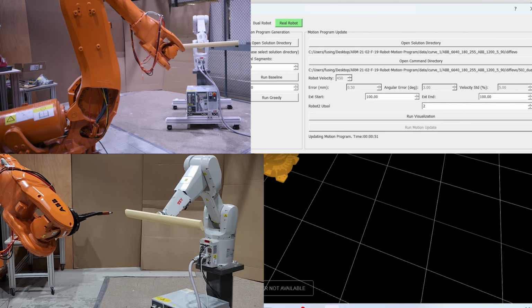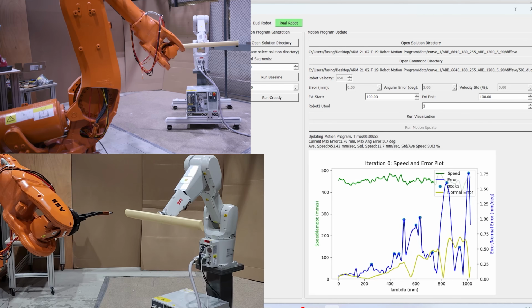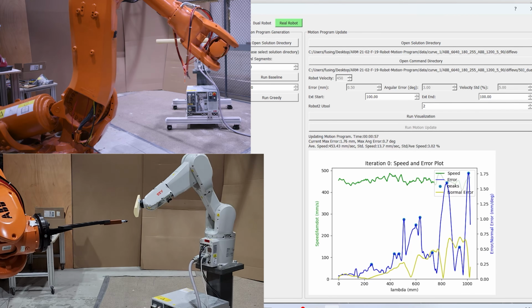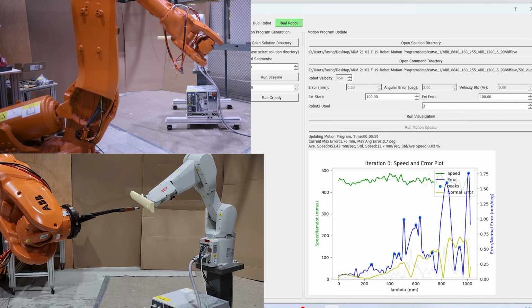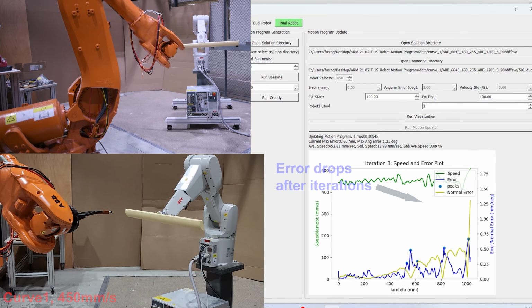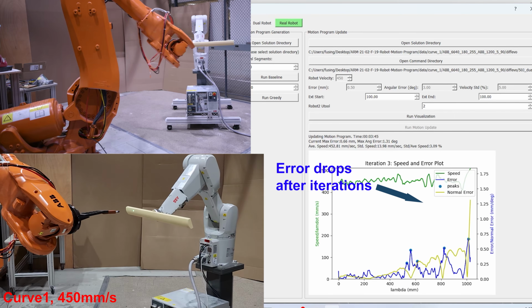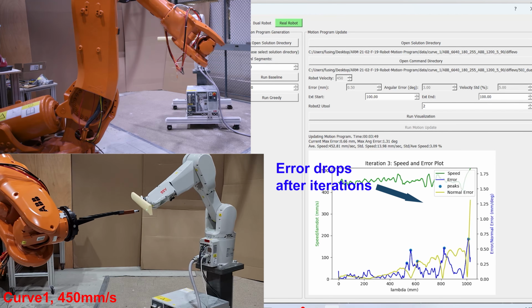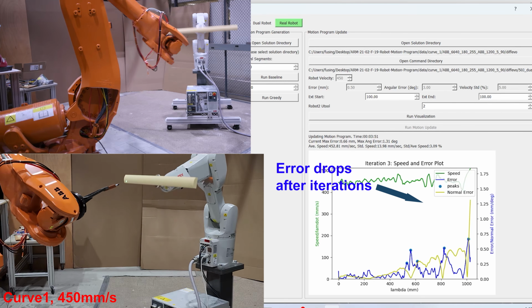Industrial robots can only achieve certain tracking repeatability. For example, ABB IRB 6640 has the tracking repeatability of 1.06 mm. We therefore evaluate the executed trajectory over a 5-run average. We used a laser pointer as the mock spray gun, pointing directly onto the parabolic surface.